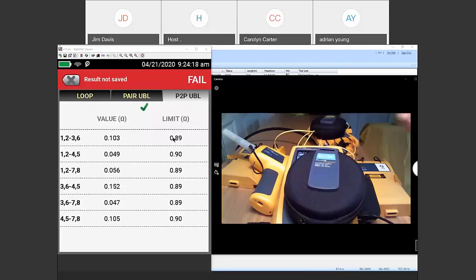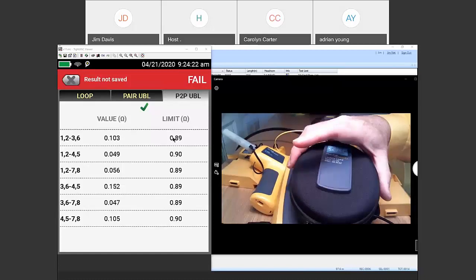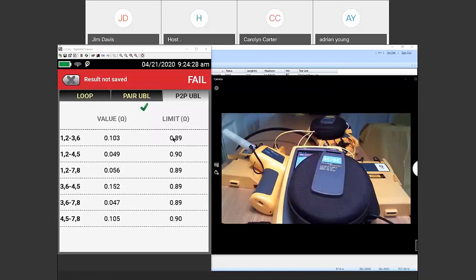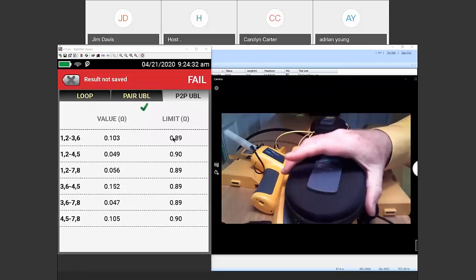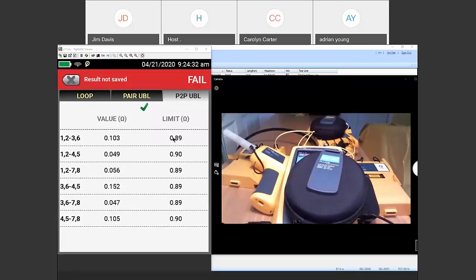Does it need to be 100 meters? Probably not, but 100 is a nice round number to subtract from the measured length. The defining factor of how long your launch fiber is, is the pulse size that you're using. If you want to measure that first connector, you need a launch fiber that's long enough to support the entire pulse that you're going to put into it. When we're measuring a short 100 or 200 meter link, we use a very short pulse, 3, 5, or 10 nanoseconds. They're measured in time, just because engineering.